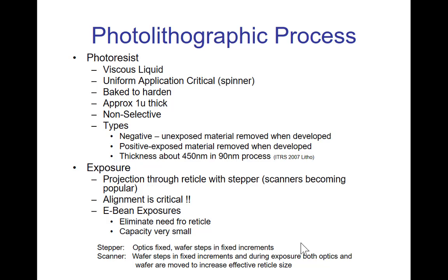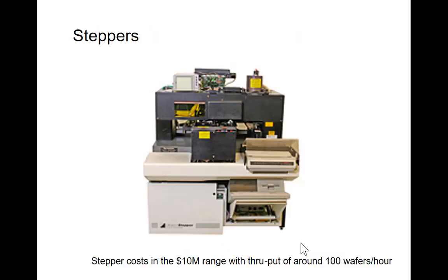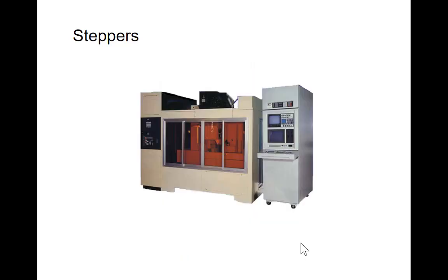But on the wafer, you have many different dies you are going to make. So one place you expose it, you move to another location, you expose it again, etc. Then you use a stepper to do that, and this stepper needs to go to the right locations very accurately. So these steppers are very expensive equipment.